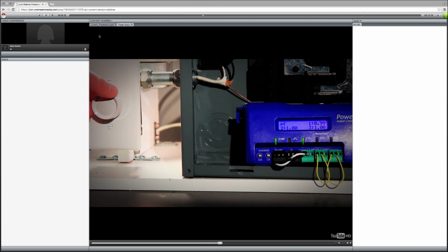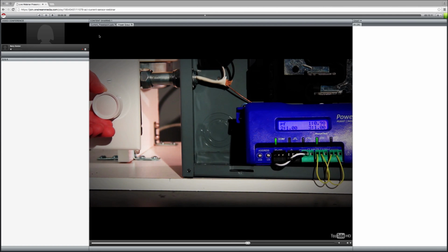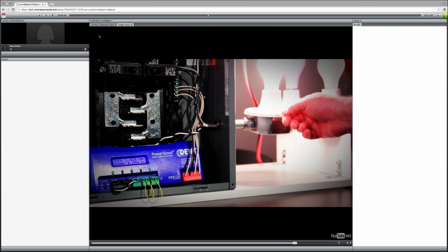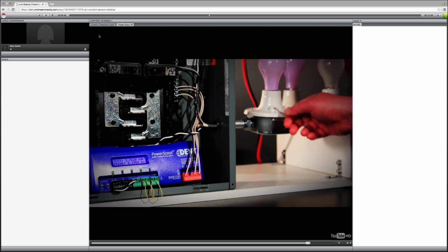We're showing the display of the power factor for all 3 phases. Phase 1 is changing with the adjustment of the dimmer, and phase 2 and 3 both display as 1 since the meter inputs are shorted together to avoid the meter picking up stray noise from the outside atmosphere. We then move on to the display of the overall system kWh and the peak demand kW. Note that as each of the light bulbs are turned off, you can see that the kWh usage slows down since less energy is being used.